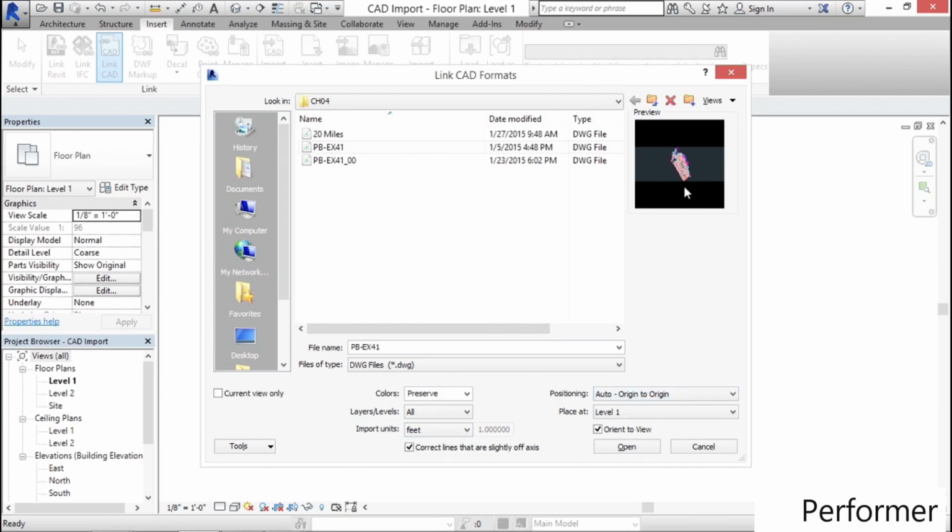Now, what I want you to know about this file is, you can see the preview here. Well, the origin is actually way over here relative to that file. So you would expect that we would get the same warning. In fact, that origin is nearly 200 miles away from the site plan. So maybe it's like a state coordinate system. You sometimes see that with civil files, where you're building the file, but they actually have the origin based on the state capital in another city.